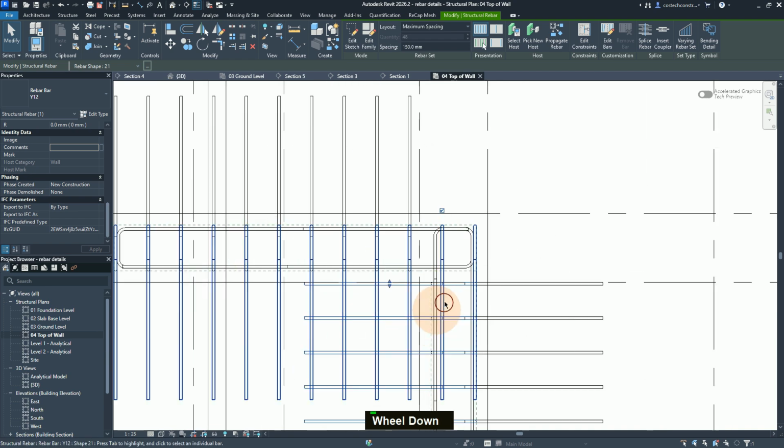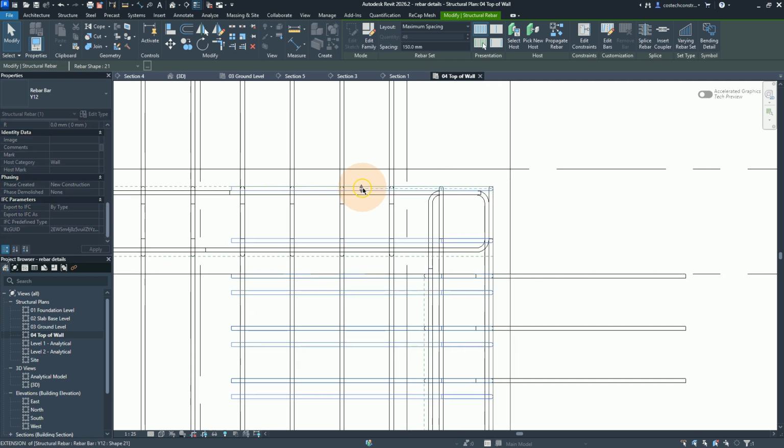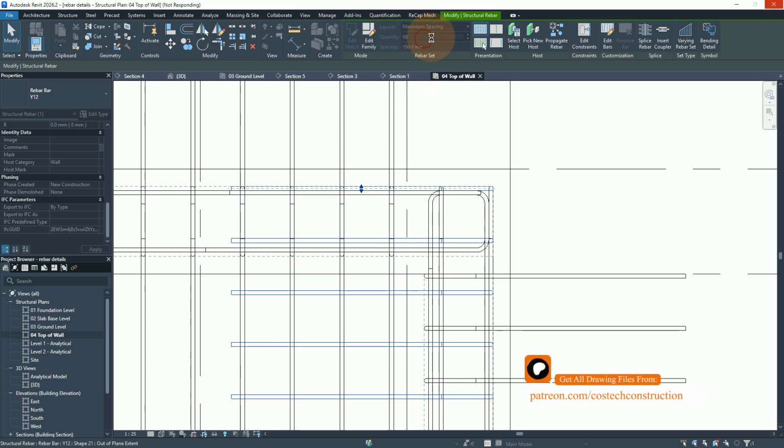Okay, so this one is for the near face. This one is for the far face. We'll extend it. Now you see that it terminates here. We should have another one up to this edge. So I'll select it, then snap it up to the cover. Snap it there to the cover like that. And now we see that we have a quantity of 50.